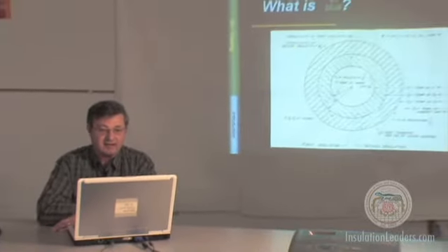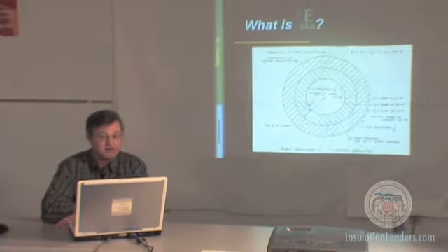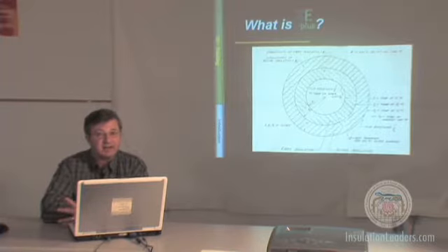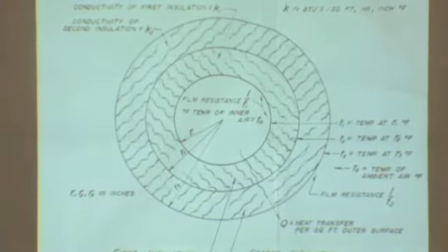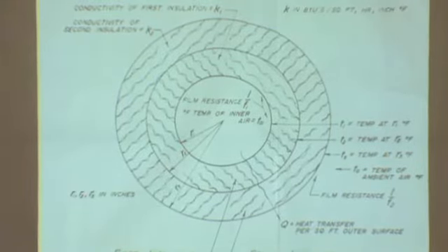For example, we're showing here a pipe which has 2 layers of insulation on it. It's got an inside temperature, some fluids inside. It's got an outside ambient condition. 3EPlus goes through the calculation of BTU heat loss in this system.